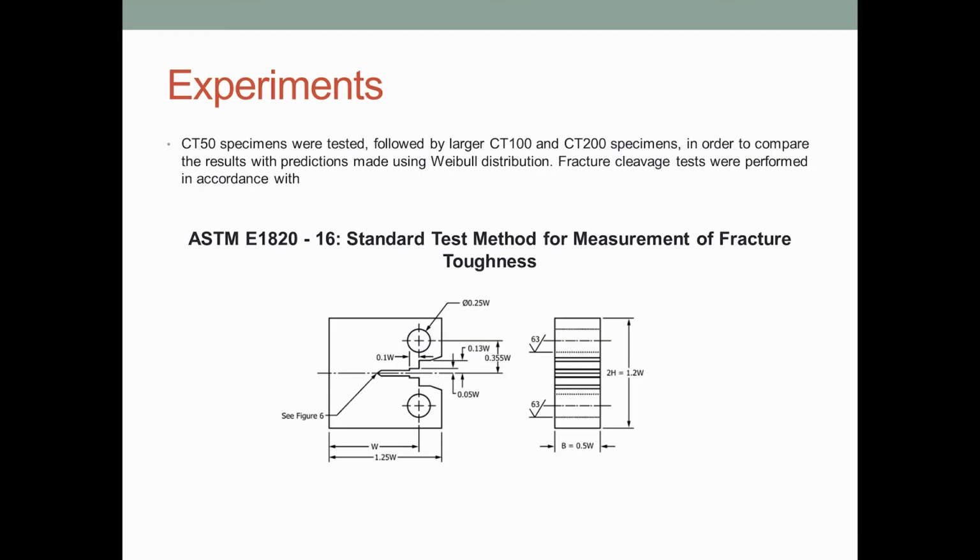Now I will say a few words about our experiments. We performed the testing on the CT50 specimens. And in order to compare the results with the prediction that we made using Weibull distribution, we did the testing of larger CT100 and CT200 specimens.